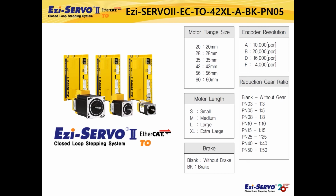A gearbox and a brake can be applied from a NEMA 17, 42mm size motor, to a NEMA 24, 60mm size motor. Gearboxes are planetary gearboxes, and gear ratio can be selected as shown in the table. The brake is a non-excitation type that activates when the power goes off. For example, you can use it to prevent the Z-axis load from falling. Please refer to the catalog for details.